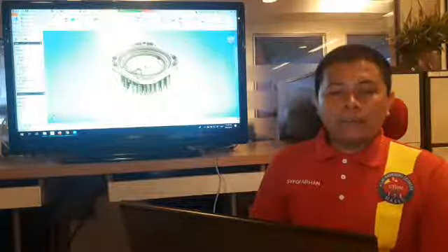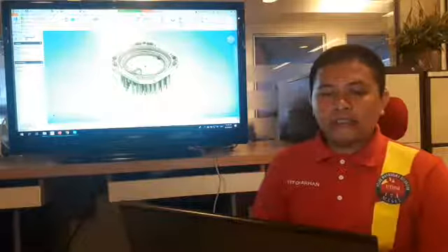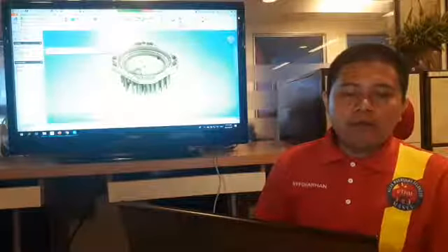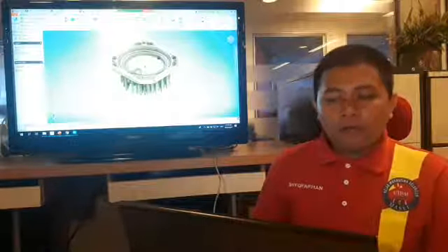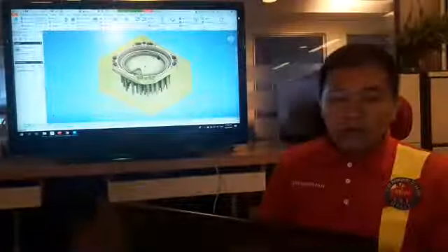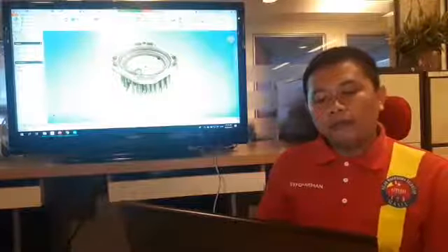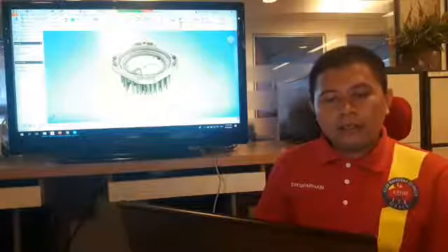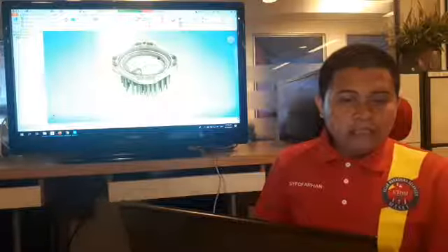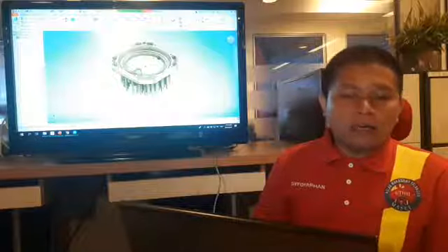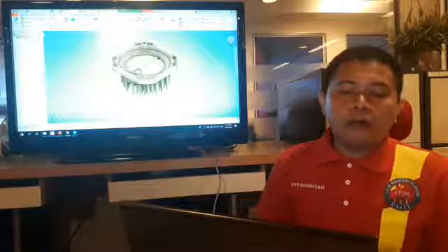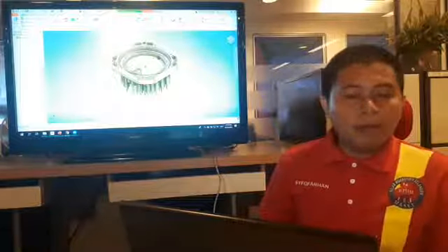Okay, so another tab for the setup is post process. Normally the machine can read the file that you name with a 4-digit number. For example, in this case, I want to make it a 4-digit number. I just simply use 1122, for example, and hit OK. Then you can see my CAM model already has one setup over here. For example, this has become the default setup, setup 4.